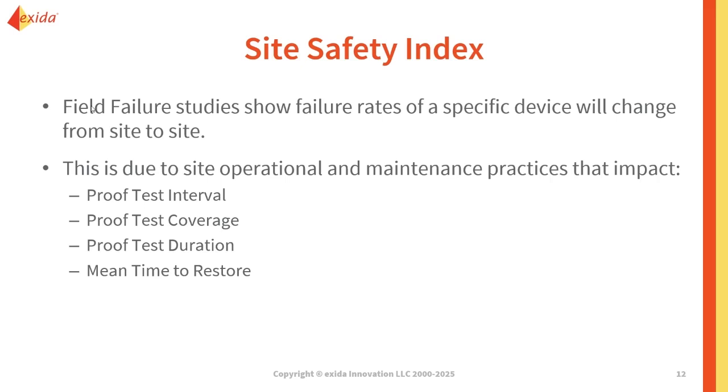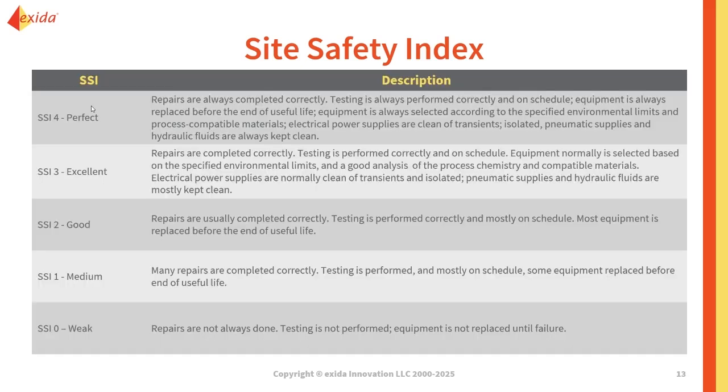results in a failure? So our practices on site determine what actual safety integrity we're meeting for our safety instrumented system. And the failure rates of a specific device will change from site to site based off of site practices and how well they're able to keep up with these tasks.